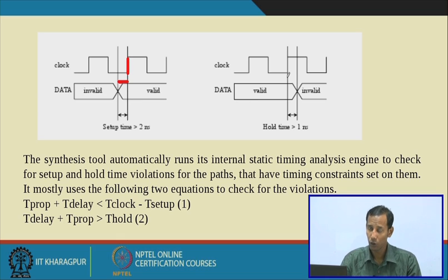So what is hold time? Hold time is that, suppose this clock edge occurs. After the clock edge occurs, what time does the flip-flop require to recognize the data properly? This time is known as hold time. Here you see that hold time is greater than 1 nanosecond for this example.